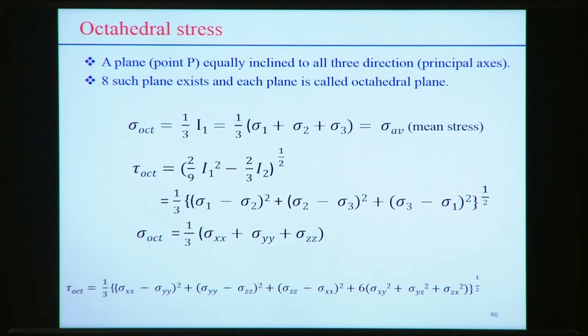Now octahedral stress is one of the main components, and it is more useful specifically when we try to analyze continuum plasticity. So in this case octahedral stress is more significant, but what is the basic idea of the octahedral stress here? The octahedral plane is equally inclined, so for example point P is equally inclined to all three directions with respect to the principal axis. So with reference to the principal axis, if a plane is equally inclined to all three directions, that plane defines the octahedral plane.